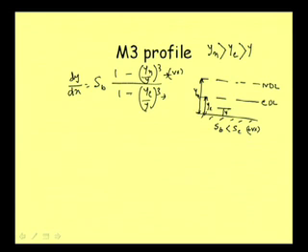So 1 minus something greater than 1 will also lead to a negative value, and SB value is of course positive, because we are talking always about mild slope which is positive. Then negative in the numerator, negative in the denominator will make the total ratio positive, negative by negative is positive, and SB is positive.